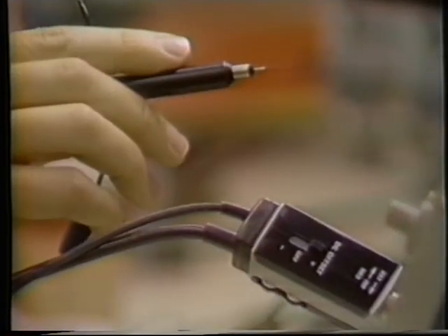The FET gate stays in the middle at 0 volts. Thus, if we're looking for 1 volt AC riding a plus 10 volts DC, our FET bias could still be at 0 to give an accurate reading of only the 1 AC volt. Well, so much for theory.